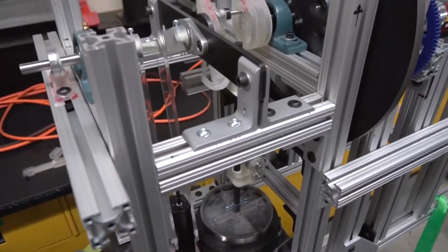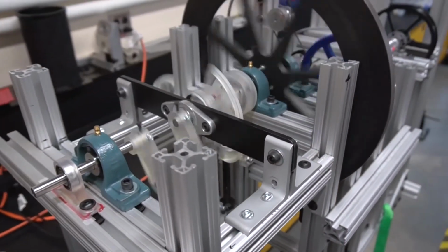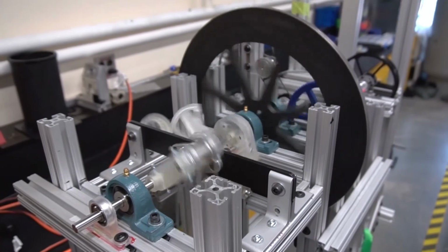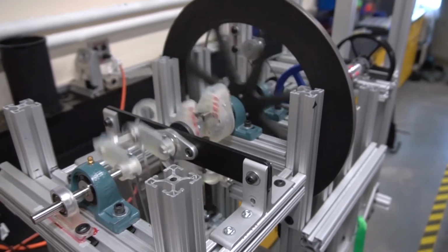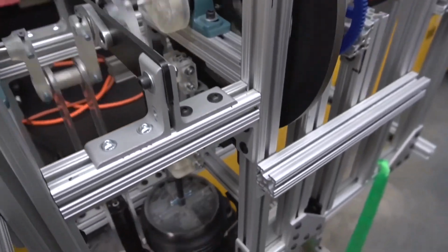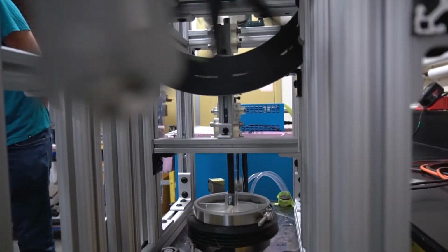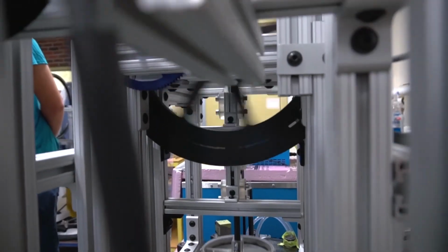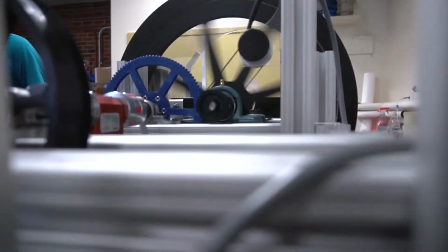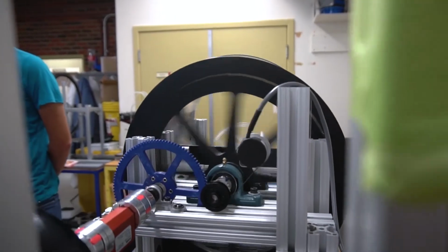So you can see here on the top view, the actual movement of the power piston is linear in an up and down fashion and is transformed into rotational motion, which then we can connect on, for example, an alternator, and from there we could generate electricity from it. So the spinning disc there is a flywheel. The flywheel is what helps keep the motion of a Stirling engine constant.